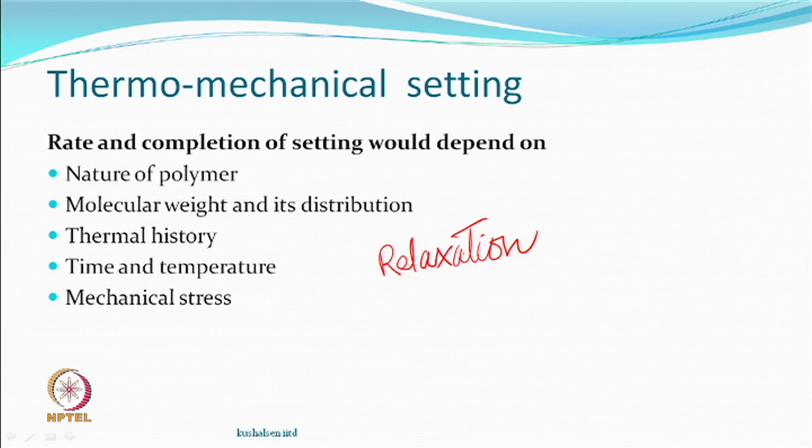For example, of the yarns or of the fabrics, the heat setting sometimes is done in a very relaxed position or in a taut condition, and they believe that if you heat set in a stressed condition, then the orientation of the crystalline regions as well as those of the amorphous regions will be high. You may want it, all right. The molecules may not like it, but you want it. And so, what is the amount of stress that is added?